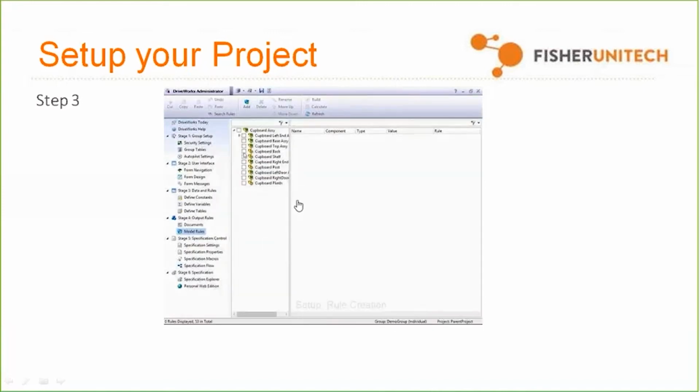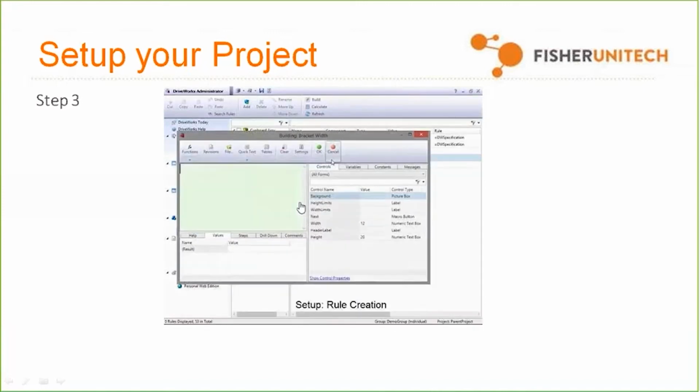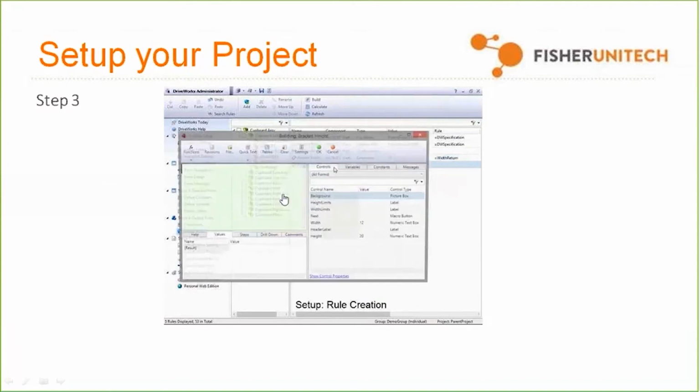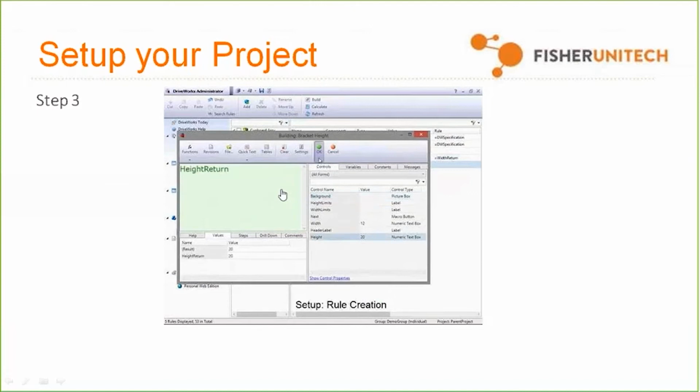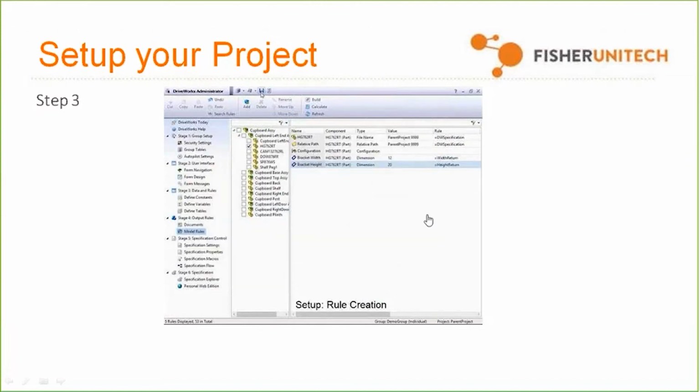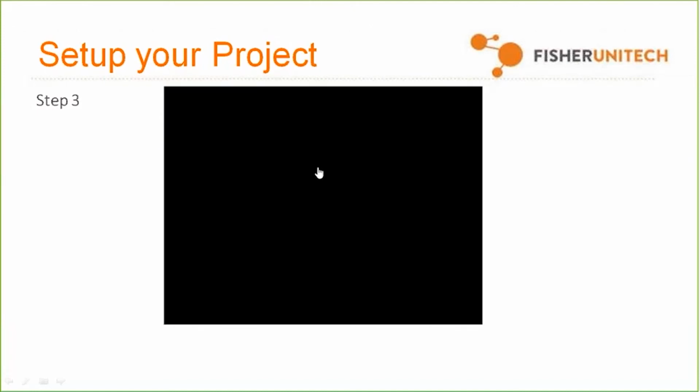I'll go ahead and click go here, and as you can see, we're going to open that bracket up, and you have a bracket with height. We're connecting it to the form controls that were made on that form. And so now when an end user comes and puts in a width and a height on the form, it connects directly to the dimension inside the actual model. And then when they create the configuration, those dimensions will be different based upon what's been inputted.